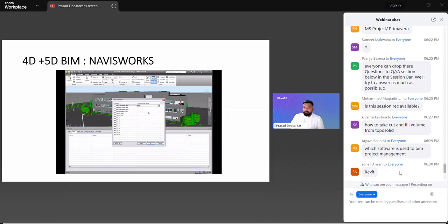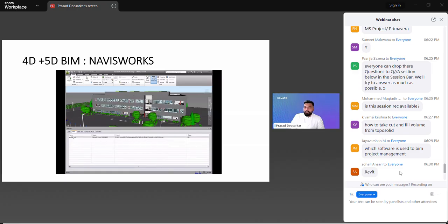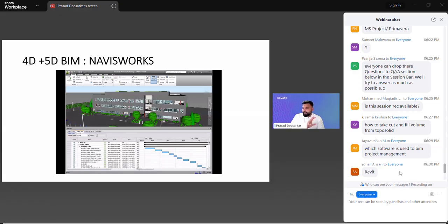You need to link it. So you need to link it with text. Need to link the dates. Like you can see on the screen, you can link a planned start, a planned end, a finish, and then once you click OK, you just need to rebuild the tasks, and then what you will see on the screen now is going to be the same exact schedule that you were seeing in Microsoft Project. Now you can see it in your particular BIM software.